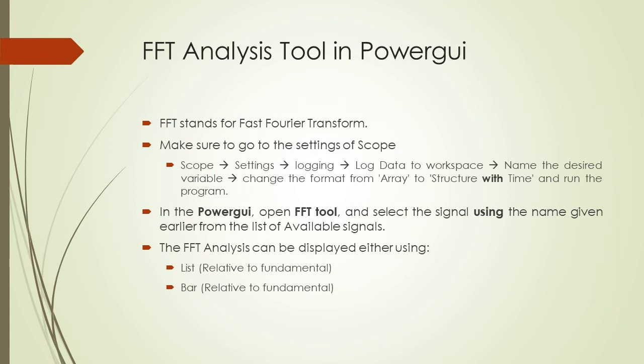The fast Fourier transform, FFT, is an important measurement method. It converts the signal into individual spectral components and thereby provides frequency information about the signal. The FFT is one of the features integrated in the Power GUI block. To use this feature, the following steps should be followed.